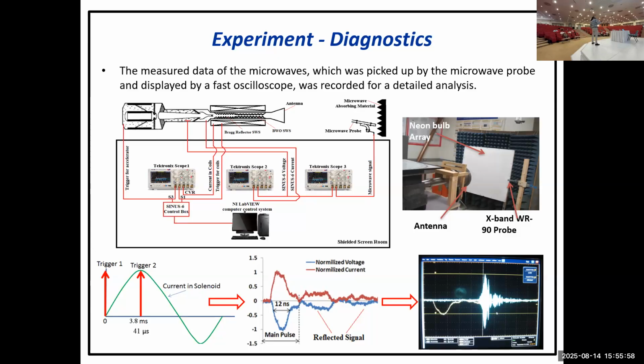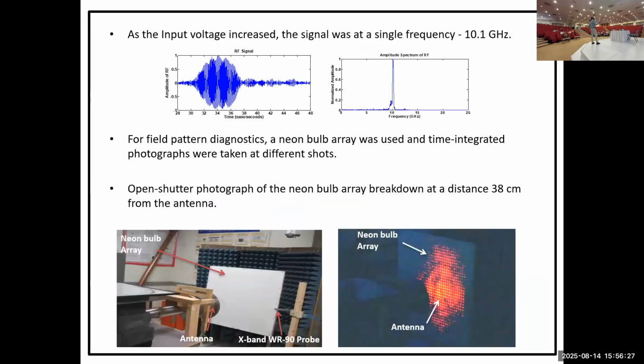Now this electron beam will go through this slow wave structure, generate RF, go back here, reflect, and transform the mode to TM01, and you're going to receive it. All of this is just a flash, on a nanosecond scale. This is the RF signal that we receive at one of the oscilloscopes. You have to take the FFT of this in order to check your frequency of generation. Okay, I think this is a good point to show you the video of the pulse.